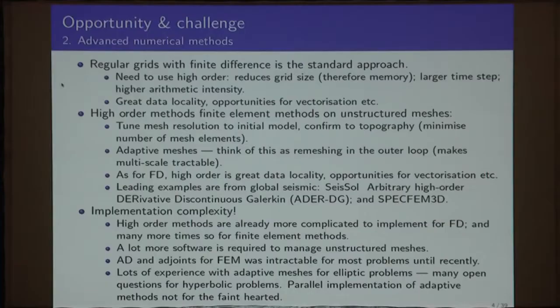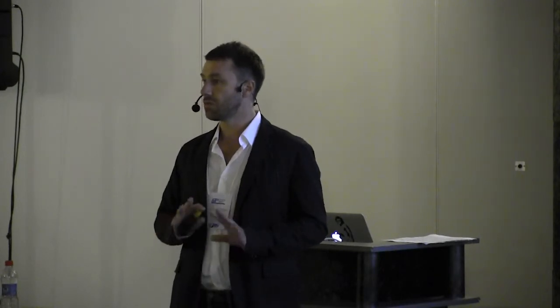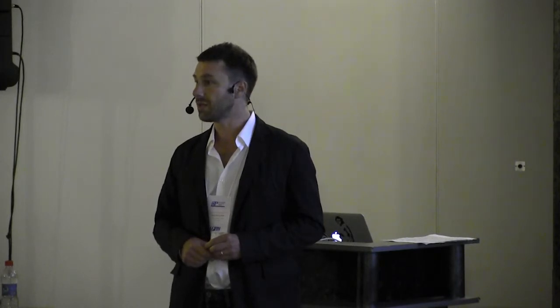If you compare a low-order finite element method to finite difference, the finite element method is going to look terrible. It's low order, it's completely memory bound, and you only achieve a very low percentage of the peak performance of the machine, something around 5% of peak performance is typical.